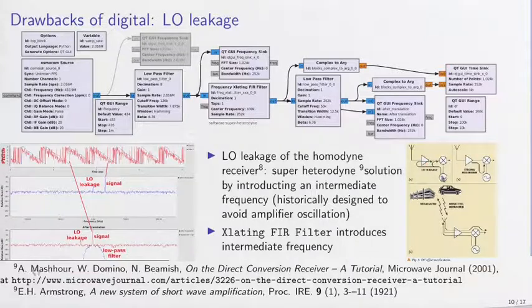So this signal at this frequency here, by definition, will be at the same frequency as the signal that is amplified again over here. And if we mix a signal at the local oscillator frequency with another image of its local oscillator, it will create a DC component. Another example is this signal being radiated by the antenna, returning to the antenna after being reflected on static targets and going again through the amplifier, so being amplified, which will create a DC offset.